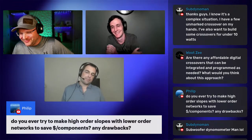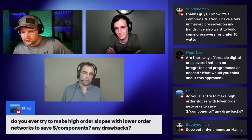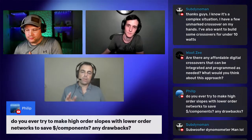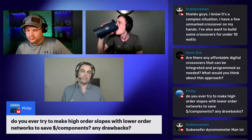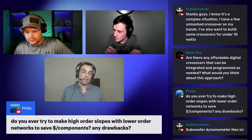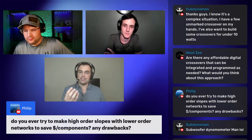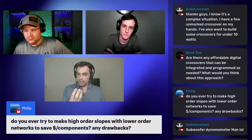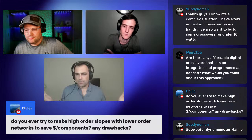Do it. So Philip, absolutely. It's not really something you can control though, okay? Because what happens is your drivers will already have their natural frequency response shape. Okay, so a tweeter is a great example. A tweeter is a very, very small driver in a sealed box. So unless the box is very small or very large, it generally has a 12 dB per octave roll off, somewhere usually around 1500 hertz.